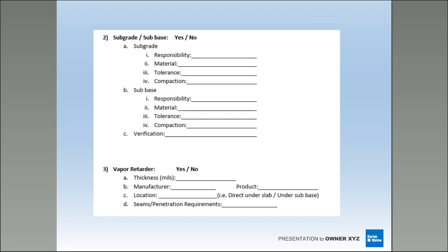As for a vapor retarder, that's important too. Are you putting an underlay under there, a 10 mil, a 15 mil? Are you taping the joints? Are you taping all the penetrations? Anytime you put down a vapor retarder, whether it's any brand, I could go through all the brands, but we won't, it's going to affect your curl and shrinkage on that slab. As a polisher, and we'll get into it later in the slideshow, it's going to affect your timeline on when you're going to want to get in there, because there are some things that you're not going to avoid that are going to come up.